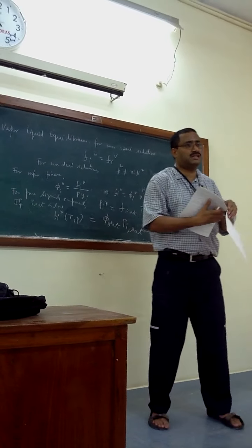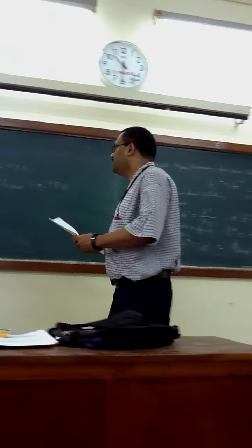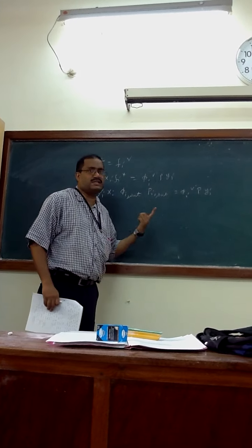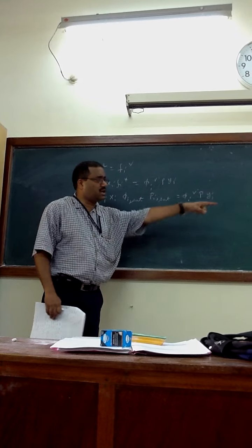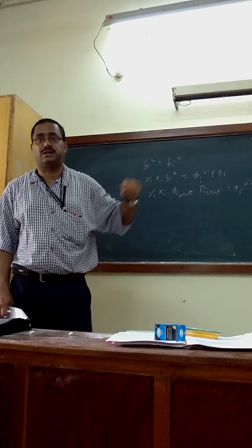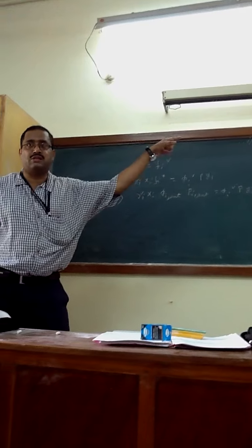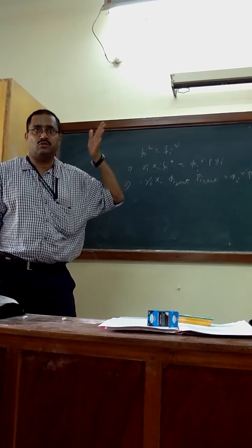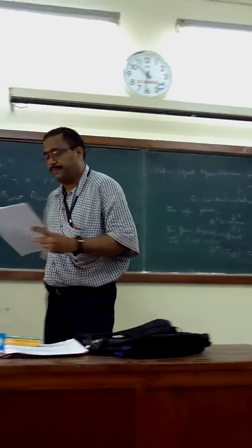So far nothing much I have done. What have we assumed here? We have assumed the pressure in the liquid system is very low, and P sat is also very low. So they are very low. That's why the integral can be neglected. The third case I will show is when the integral cannot be neglected. The question was supposed to come from you. You could have asked, sir, what will happen if the integral is not neglected? Can't you solve it? That's called the high pressure approximation. Yes, you can solve it. I will discuss that, and with that I will end the vapor liquid equilibrium.